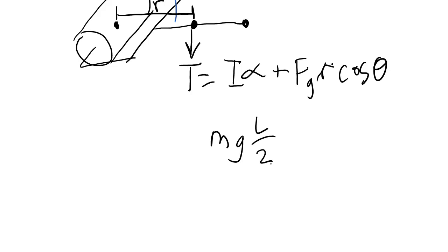For the cosine of theta, since we're calculating the torque requirements for the motor, we have to calculate the torque requirements in the worst case scenario. The worst case scenario is the position that we actually drew the link and joint in the picture. In that case, the cosine of theta is 1.